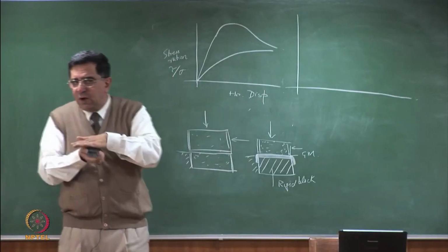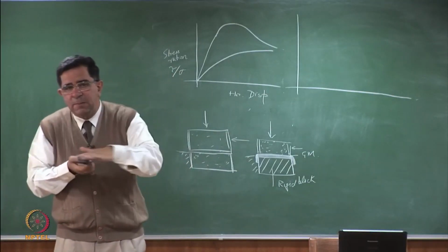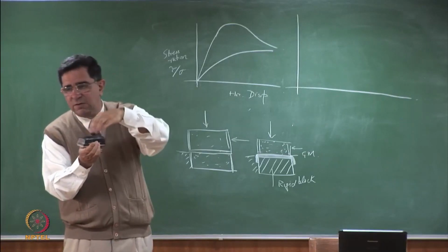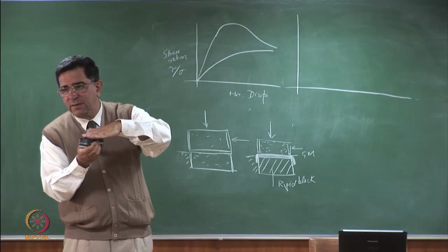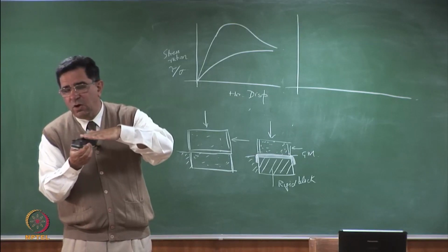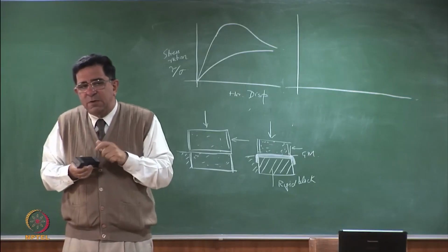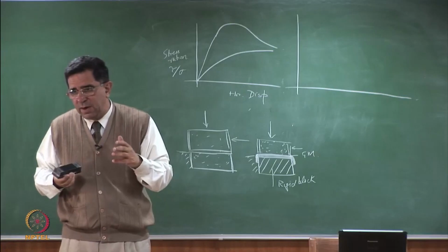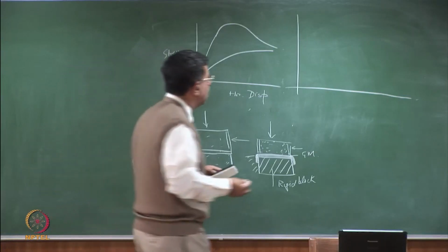An interface shear phenomenon is a slippage phenomenon. This is the bottom, this is a geomembrane, a smooth geomembrane, my soil is here, I move it, I'll get a friction angle or an adhesion. So will it require 10% strain to get a peak or a 5% strain? No, the peak comes much earlier.